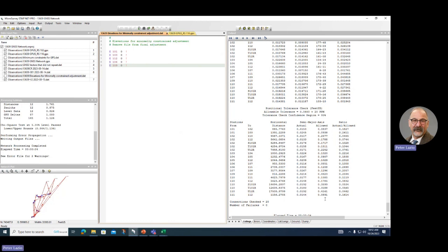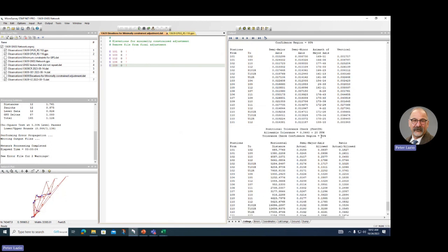So I could say with full confidence, even though I couldn't repeat my baselines to the 20 parts per million, because I also added my total station observations in there, I am legitimately passing second order class 1. I'm allowed 800s. I got 15,000s. Yeah, or 800. That wasn't just a pass. Every one of them was a significant pass.